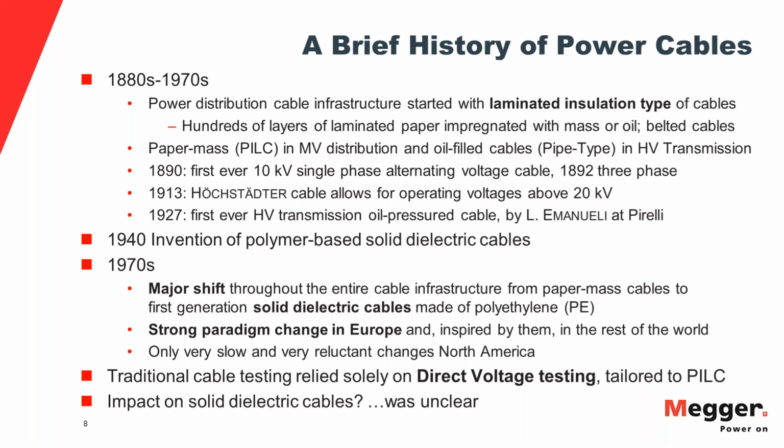However, very interestingly, the same change did not really happen in North America. It's actually a very slow change. You still have a lot of PILT in the NAFTA area in the US, and specifically also in the transmission area, the 345 kV levels and higher, which internationally is all XLPE these days. You still have probably, I would guess, at least 90%, probably 95% oil-filled cables.